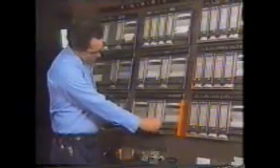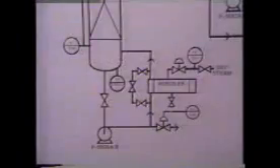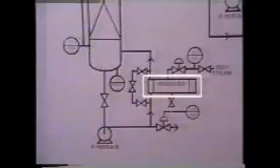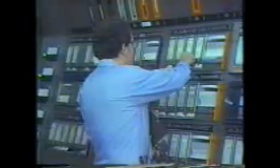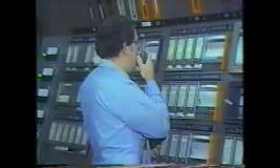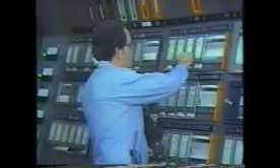Meanwhile, the inside operator moves the set point of the bottom's takeoff flow controller to 0. This stops the removal of the bottom product from the column. He will also reduce steam to the reboiler because there will be a reduced load on the column with no feed going into it. Once the column is on total reflux, the inside operator monitors the level in the condenser leg. He adjusts the amount of steam going to the reboiler to keep that level constant. At this point, the column is now in a short-term shutdown.